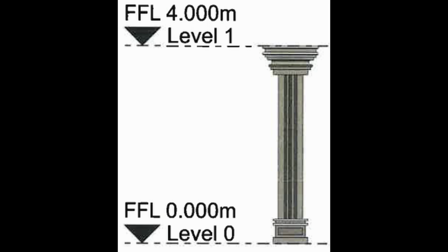Line-based families. Most components are placed with a single click. Line-based families, however, require a start and end point. These are useful for linear objects like trench heaters, cable trays, or custom duct accessories that need to stretch parametrically.